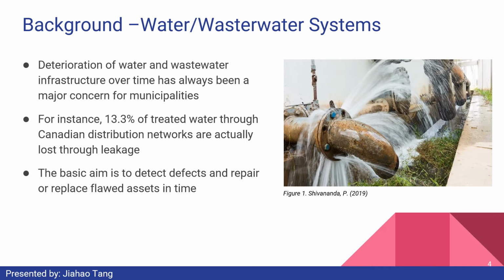A more surprising fact is that more than 50% of the leakage is caused by leaks from large diameter pipes, which only occupy less than 5% of the total number of leaks within the system. Similar situations also take place in wastewater assets. Besides waste of water, these failures can also result in other potential risks, such as contamination to the environment and also to the surrounding infrastructure. These signals highlight the significance of condition assessment to make accurate evaluation and make necessary repair or replacement in time.